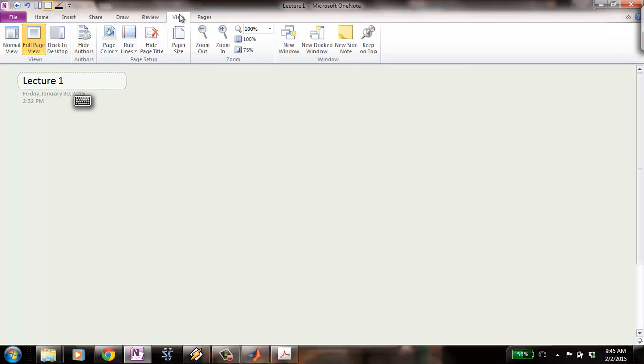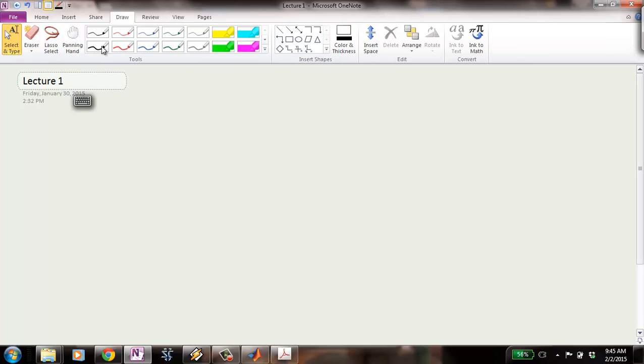Let's just, what can I do in a few minutes here? Well, so in general, we're not going to restrict signal values to be real value. They can be complex values. There's a very important reason why we're doing that. Okay, you might say, well, real-world signals are real numbers. Yeah, you don't have a sensor that gives you a complex voltage. It's got a real number voltage, right? But if you extend things out to complex numbers, the math is a lot simpler when you're doing things like Fourier transform. The Fourier transform is going to explicitly use complex numbers everywhere.